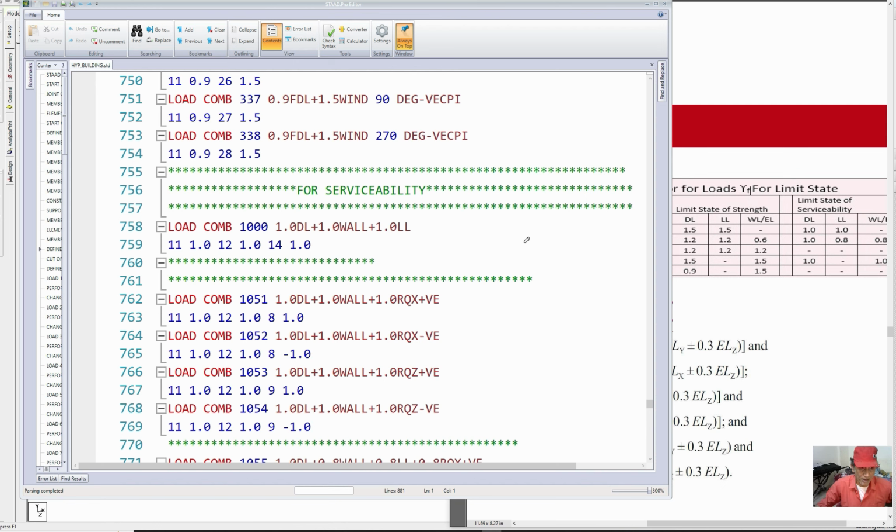For deflection estimation, dynamic analysis with a scale factor 1 suffices, because the dynamic base shears are scaled up to match up with static base shear, because the non-structural members in the building actually increase the stiffness of the building. So more seismic loads are generated because of more stiffness.